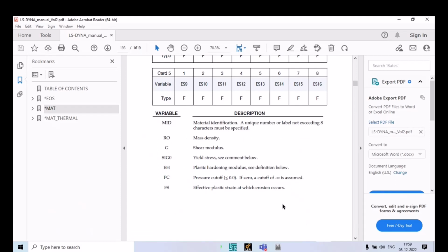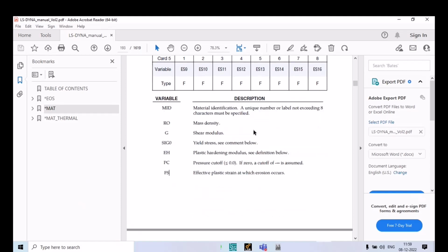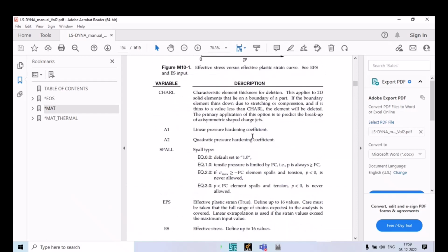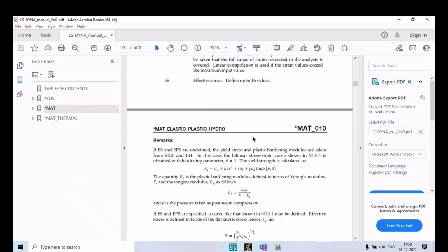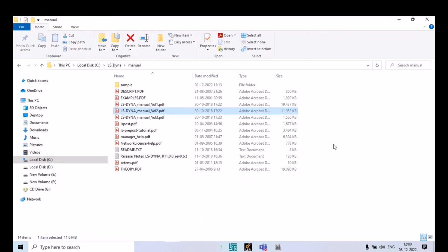But sometimes, like in Ansys also, for example, we always give only those properties that we have to test. We unnecessarily do not define all the properties. The software will ask you so many things, but we only give those properties that we have to test. According to the requirements of my solution, whichever properties I want to test in the model, those properties you have to fulfill.